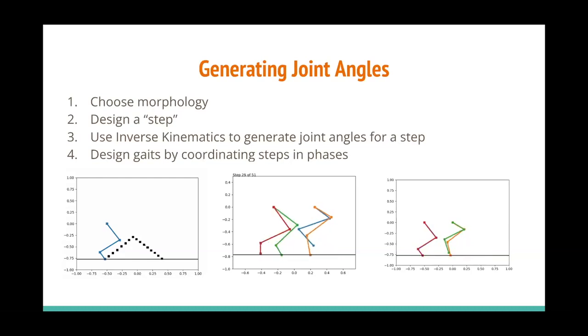So you can see each of the black squares there represents one point that we want the leg to touch in order to make the classic up and down movement. After that, we used inverse kinematics to generate joint angles for each step. So the inverse kinematics algorithm works by going bottom up through all the joints. Starting at the ankle joint, it'll try to point the effector towards the first location, and it'll go as far as its hinge allows it to, and then stop.